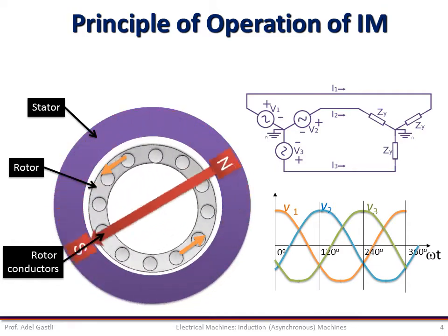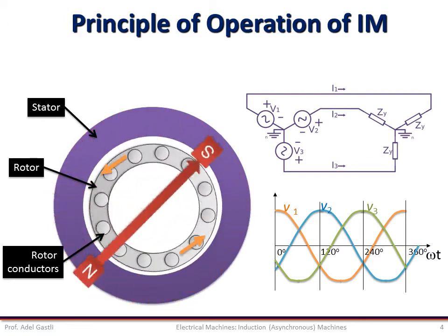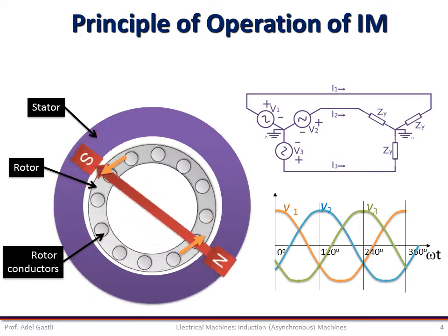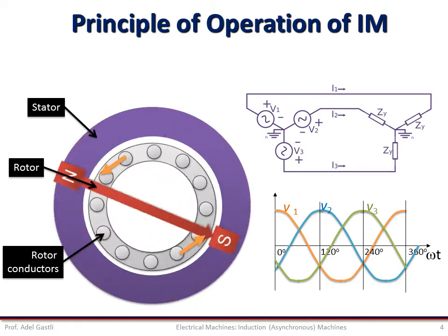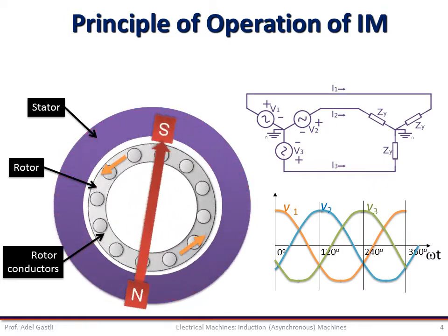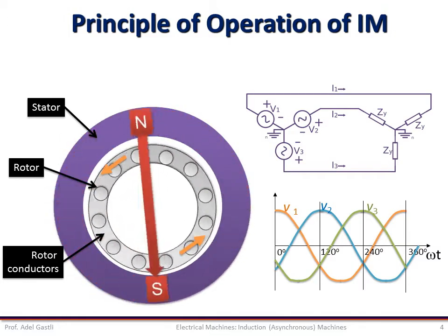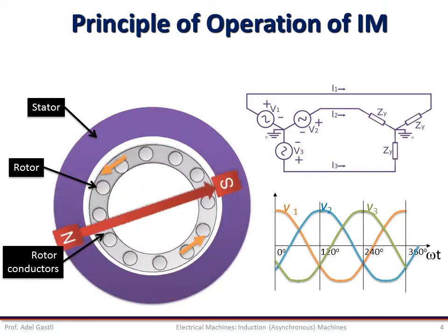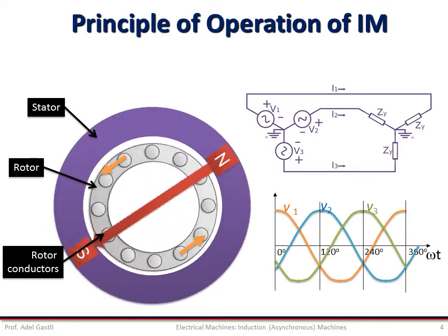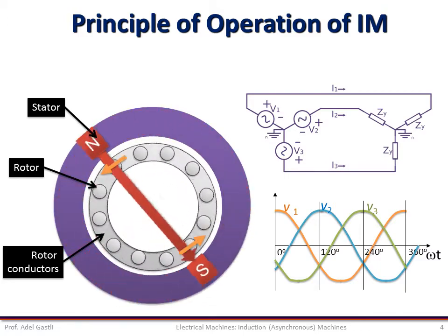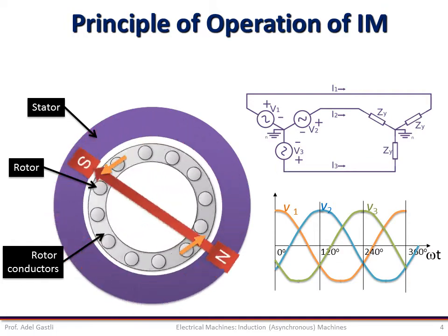So the rotor will never be able to rotate at exactly the synchronous speed because of mechanical torque due to bearing and air friction, which the motor needs to compensate for with the generation of its own torque. Note that at steady state, the load torque and the motor-generated torque must be equal so that the speed settles at a certain value. Otherwise, the speed will be increasing or decreasing depending on the difference of these two torques. Next, we'll see in more detail how the rotating magnetic field is produced inside the stator.